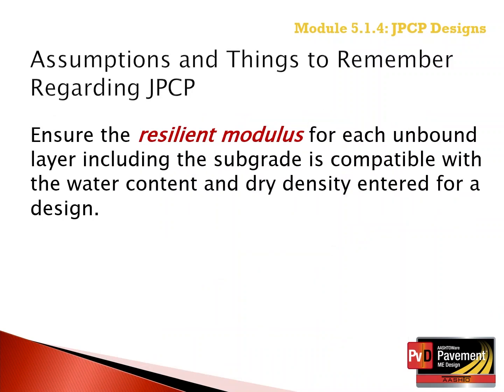Remember from Module 4.4.1 on subgrade soils and Module 4.4.2 on aggregate base materials, the resilient modulus of any unbound layer should be compatible with the water content and dry density entered for a specific design.